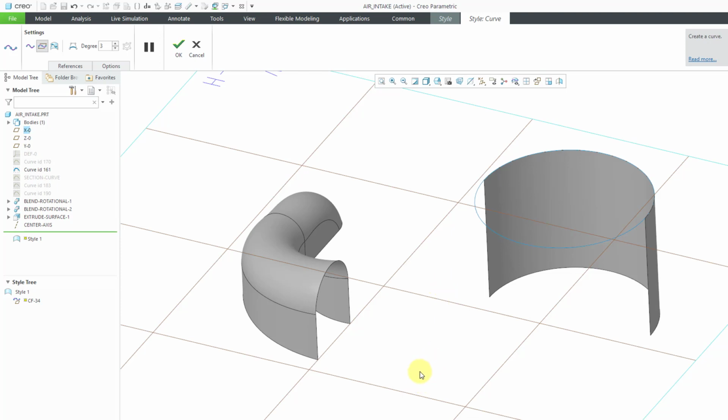And then first I'm going to create the curve incorrectly. I'm going to hold down the Shift key and lock into the vertex over here. It's hard to tell, but I can see that there's a little green X there indicating that it is a fixed point. It is locked into that particular vertex. I will hold down the Shift key again and then grab, oops, looks like I didn't get the vertex. Let me hit the undo button. Let me hold down the Shift key. I think I was actually holding down the Control key. I hold down the Shift key and there I get the vertex.